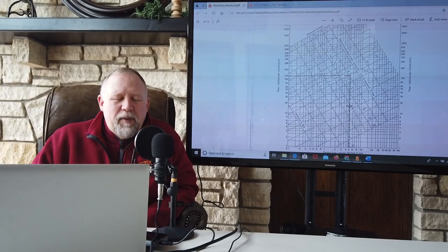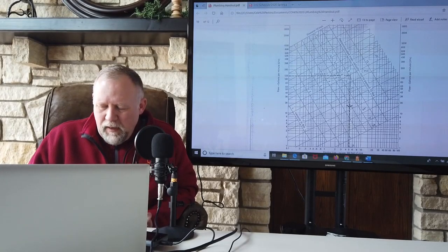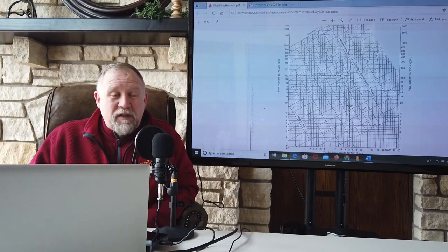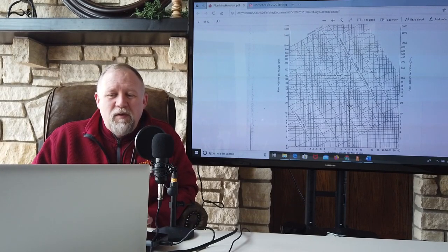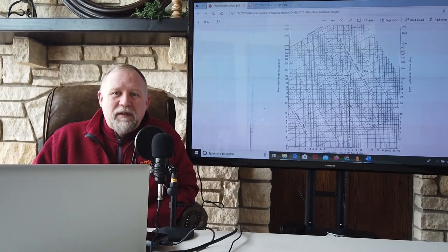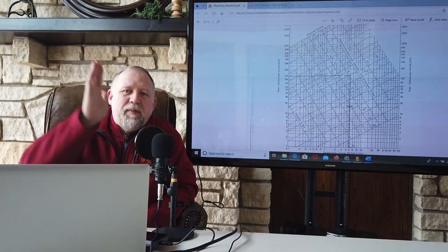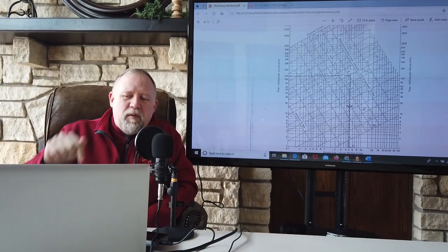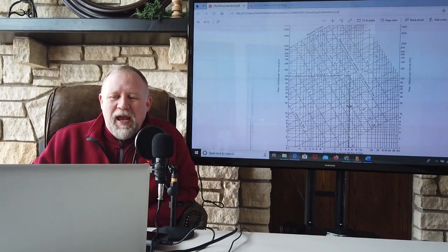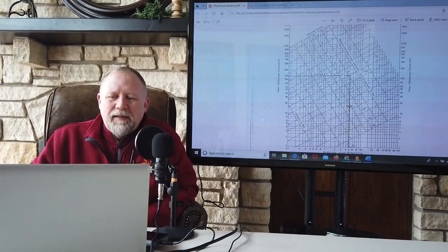Like if it was above a classroom or maybe above an occupied space like an office or something along those lines, then you use this 6. But if it's either in a shaft, like an enclosed shaft that goes straight up through the center of the building, or if it was buried below grade, we would use 8 feet per second.